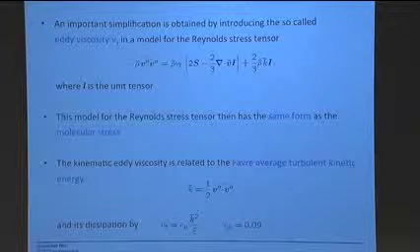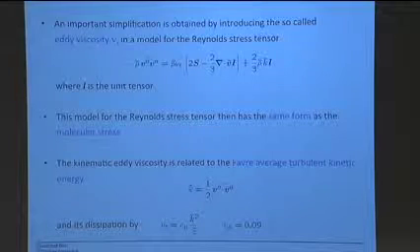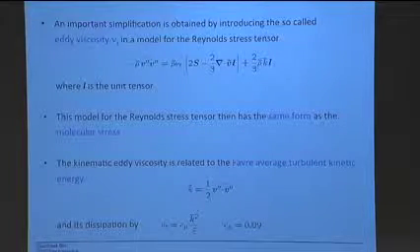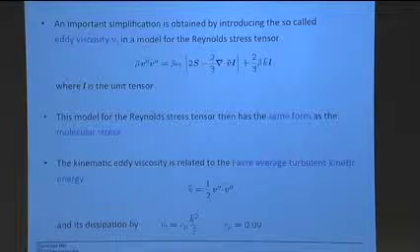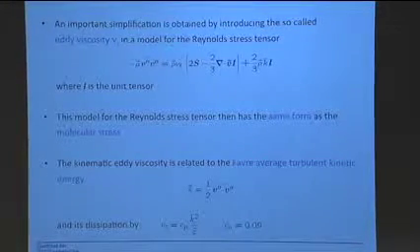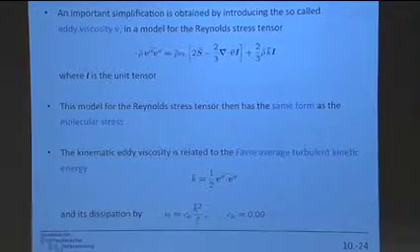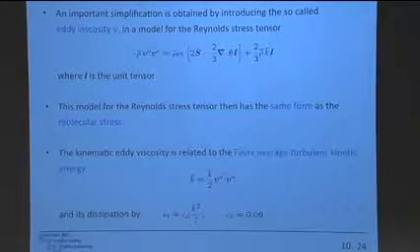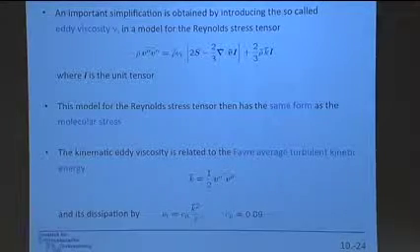Okay, what do we do with nu t? We just do dimensional analysis. We say nu t has the dimensions meter squared over second. That would be a length scale times a velocity scale. And we say a turbulent eddy has a length scale, its size, and it has a velocity scale, which is the velocity with which it turns around itself. And multiplying these two with each other gives you a model for this quantity. Okay, just scaling.